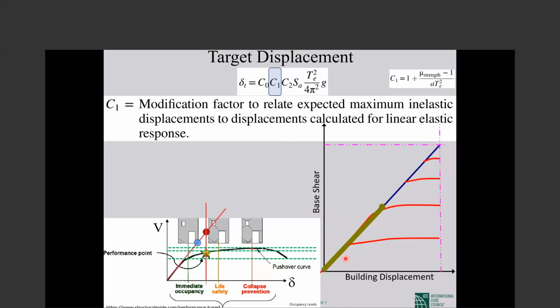So if the building is elastic, you get on average this much displacement. You reduce its strength to much less. It gets damaged, it gets this much plastic deformation. So if you let it return, it comes to here, a large residual displacement.